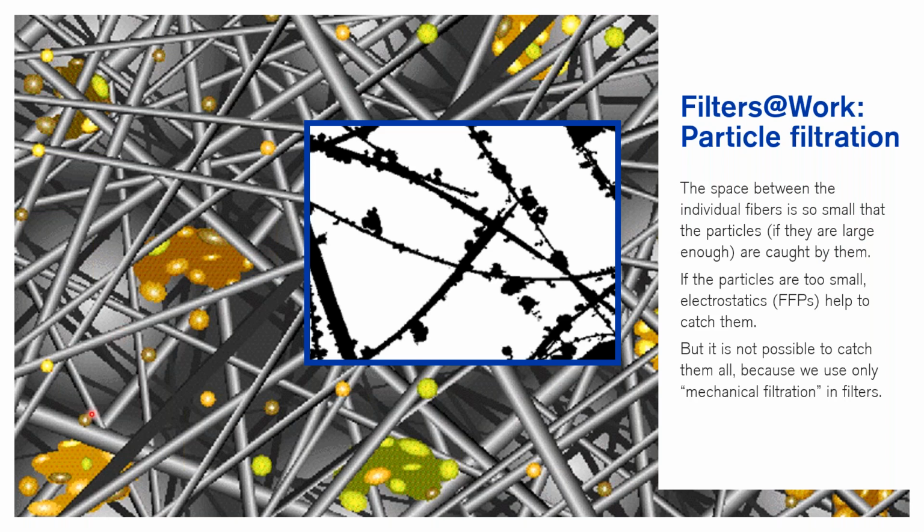You can see the brown and green background; these are dust particles that have been caught in the net. However, like I mentioned, at 0.3 microns and below they move with the Brownian effect, and these particles are too small to be captured mechanically. So the plastic properties of the filtering facepiece will help to catch them through electrostatic means.